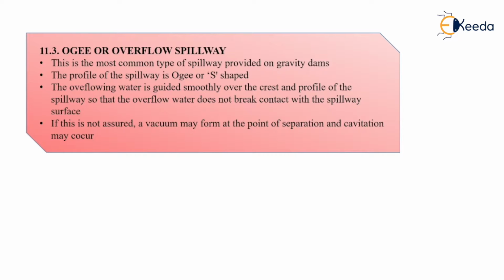At the maximum reservoir level, it will be constructed, keeping the crest level equal and parallel to the maximum reservoir level. And once the water rises, this surplus water will be carried through this Ogee shape, through this Ogee spillway.